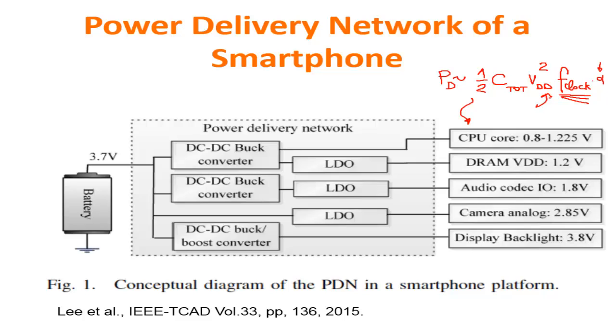You remember that the power supply voltage determines the delay time of the logic gates, and therefore the clock frequency. When you want to reduce the clock frequency, you can increase the delay time of the logic gates, and therefore you can decrease the supply voltage.